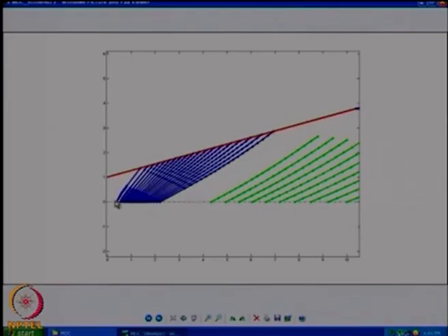Okay. So as of now, I have been solving left running characteristics all the way till here. Okay. And suddenly, if you want to switch to a right running characteristic way of solution, I can still do it, and that is what I wanted to show here. That I have given a different color. Okay. I will start solving from here. I will give a triangular patch here. Okay, this triangular patch where I will from here go to the axis. From the axis, I will now start calculating interior points up to here, and then the next wall point will be here. That I won't worry about right now.